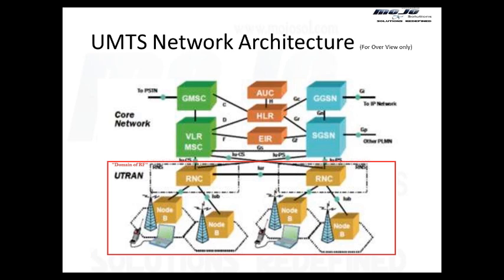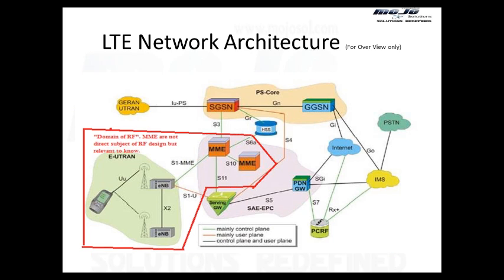And the basic difference between the two technologies, UMTS and LTE, is its air interface. UMTS used the WCDMA air interface, and LTE uses OFDMA. So these are two totally different air interface technologies, which makes the spectral efficiency of the two technologies entirely different. Note down this word as well: spectral efficiency. And the reason companies are going from UMTS to LTE is basically the higher spectral efficiency.